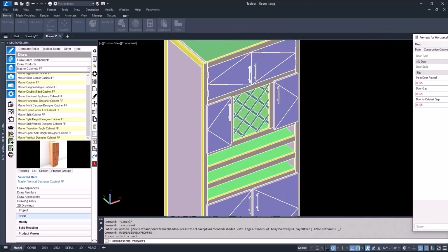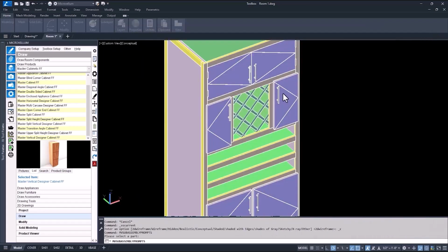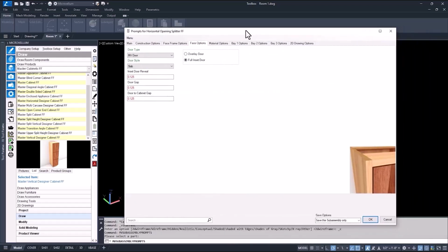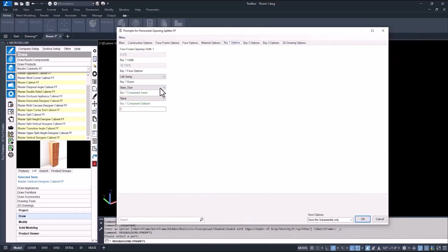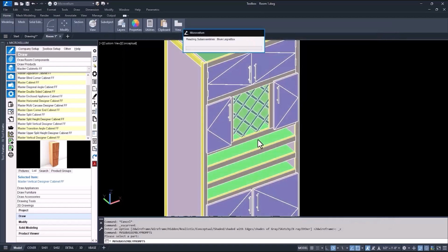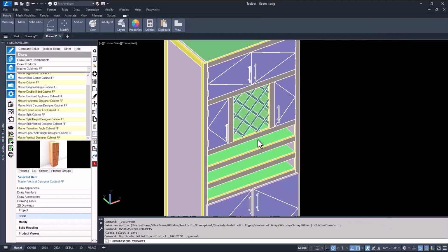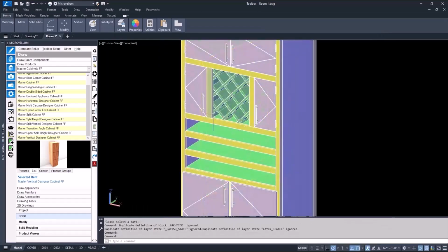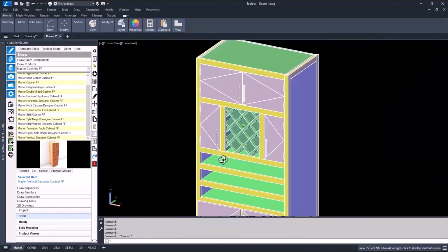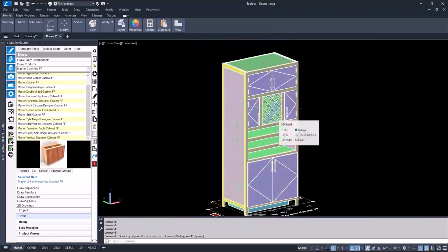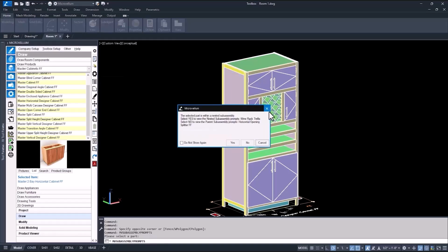And to change the handle location, since I don't like them there, I can change the door type for bays 1 and 3 to upper doors. Now this looks to the settings for upper doors to locate those handles. Now if you want the opening size or anything else to be different about this wine rack, that's when you'd select Yes and go into the nested subassembly.